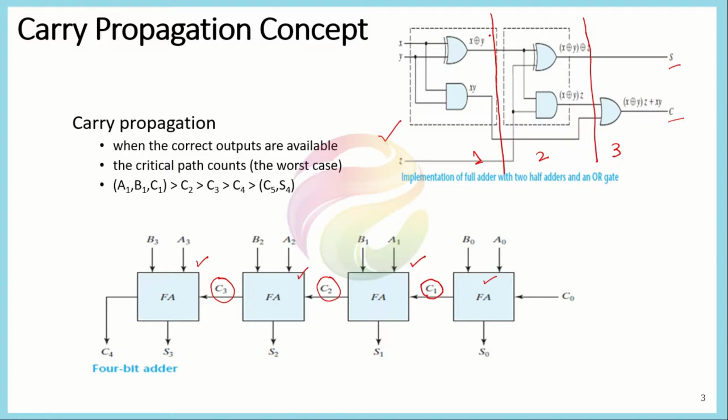After 1 cycle we would have this expression from all the full adders, from this one, this one, this one, and this one. From the second level, what we have to do is that the second level implementation of each full adder has to wait for the C0 or the carry in term, because it is dependent upon this carry term. So when its carry is ready, only then it will perform the next operation. After the first level, when all of them have performed this first step, the exclusive OR and the AND gate, then what would happen for the generation of carry?